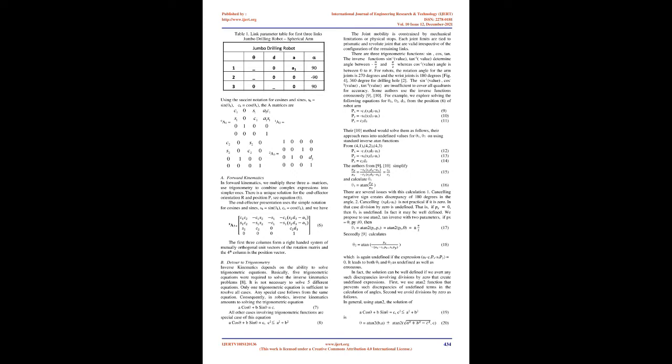For velocity, the velocity equation uses the Jacobian, t equals J times θ-dot. Forward Jacobian: velocities at the joints are specified, and the problem is to find the end effector velocity, t. Inverse Jacobian: the end effector velocity t is given, and the problem is to find the link velocities at the joints. There are 3 techniques for computing inverse kinematics. Inverse kinematics involves solving trigonometric equations. If such an equation is not solved properly, it may lead to divide-by-0 singularities in the solution.